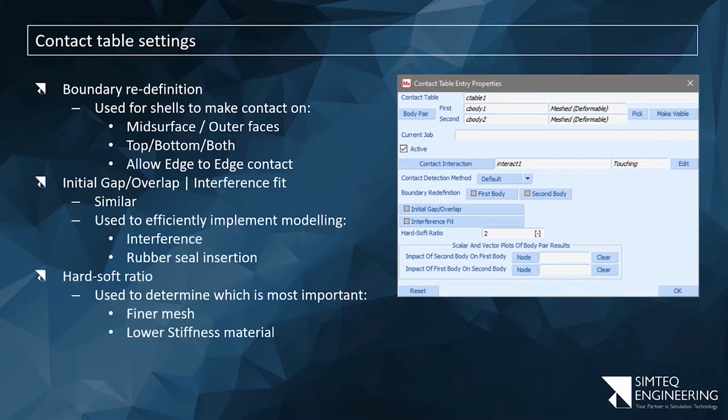But if you look at the results, there's a contact status. So in other words, that knows after one body is in contact with the other one, and it causes stresses because effectively it makes contact before the other part. Said another way, one way of looking at it would be to say we're effectively forcing a shim in between these two, but we're not seeing the shim. So that's why there seems to be a gap. It's still in contact, it still causes stresses.